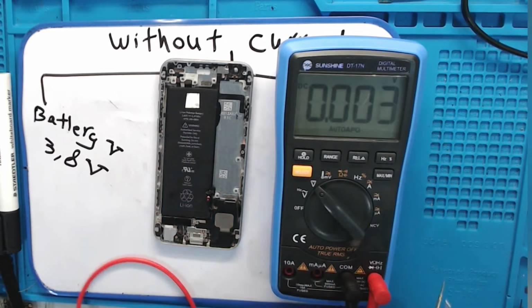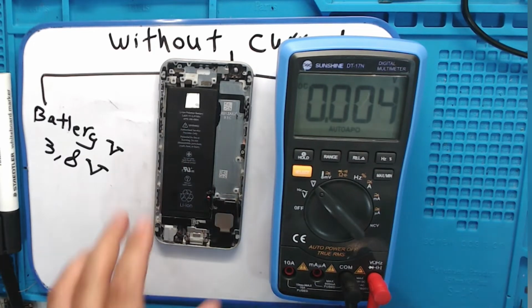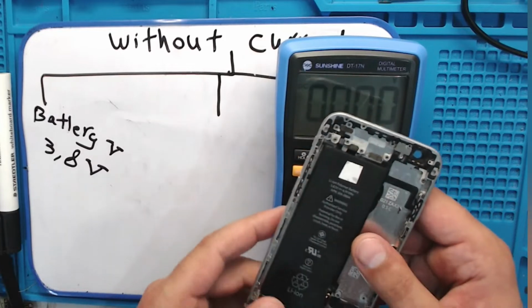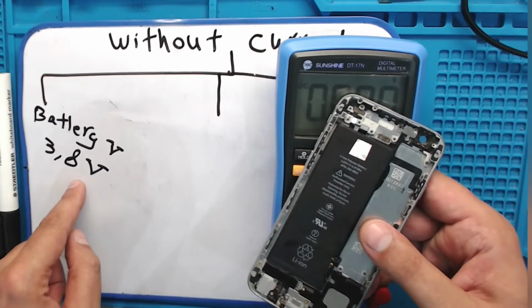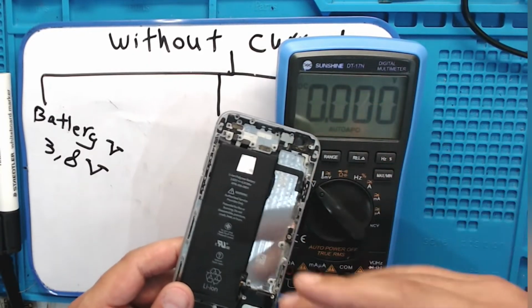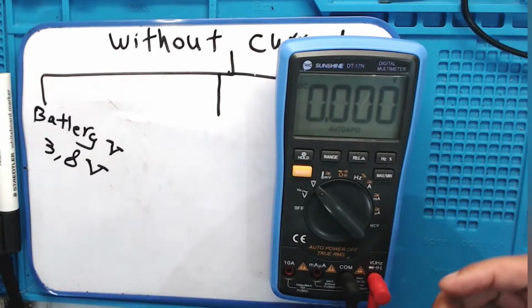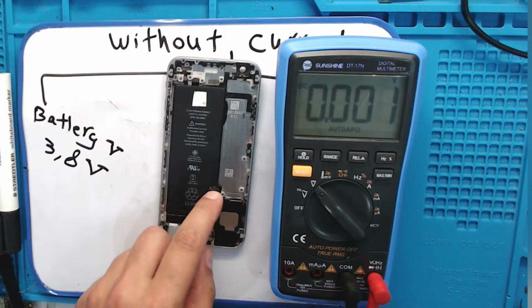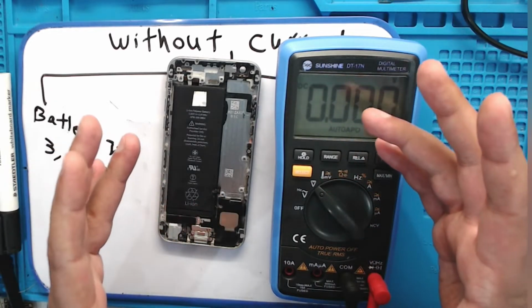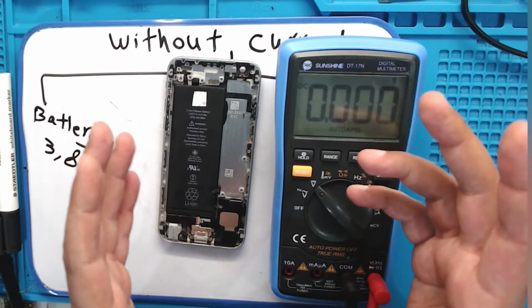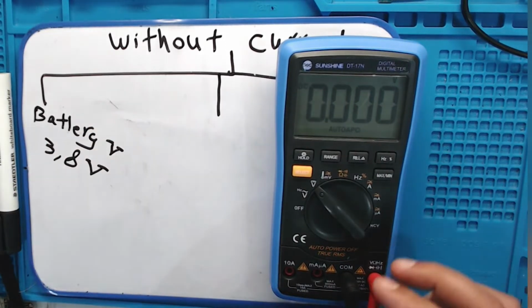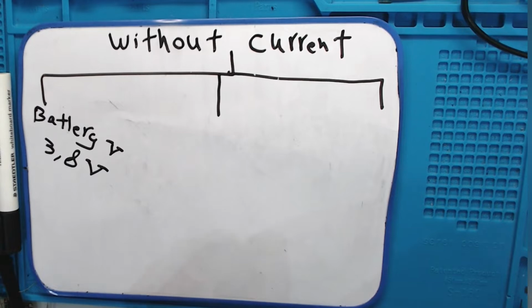This is enough voltage for this battery. If you put the screen on and connect the charger, it starts charging. But because it is lower than 3.8, it starts charging the phone very slowly. You can use the DC power supply to shock it, or you can buy a charging board, a new device, to charge the battery. That's it. This was about the first issue.